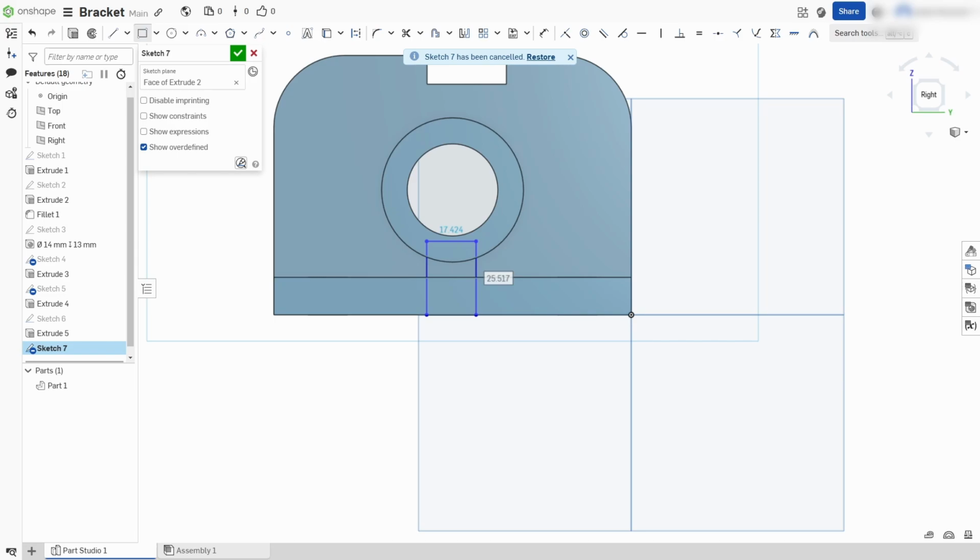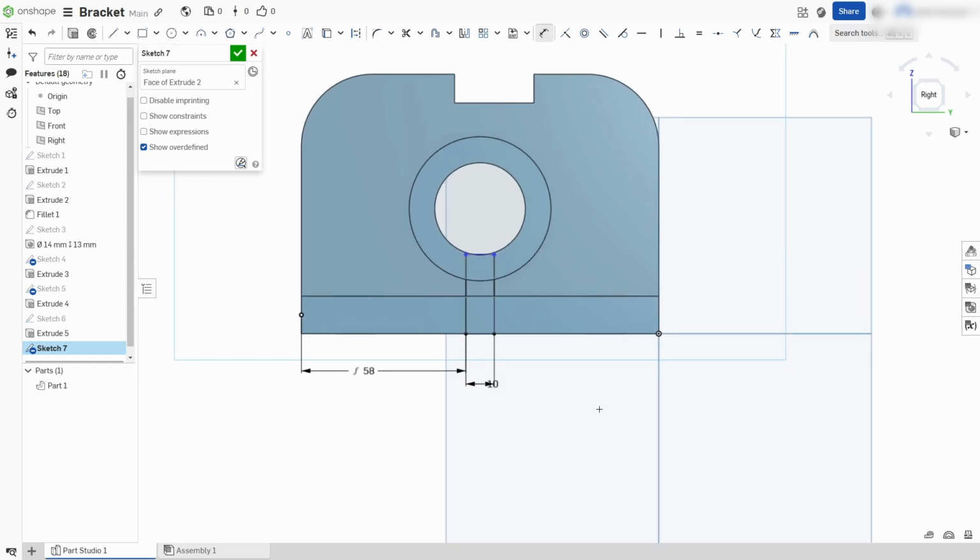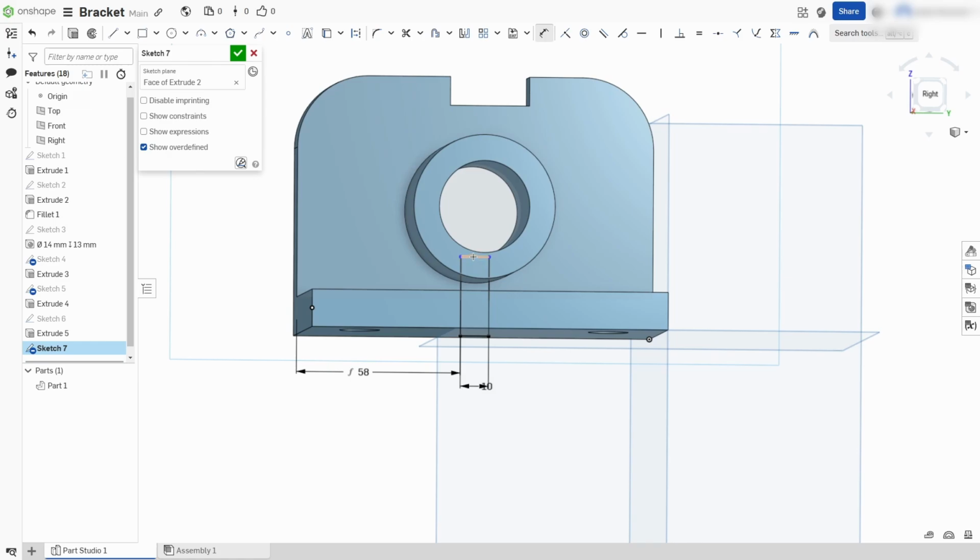Okay, and then this is 10 wide. So I'm gonna start this side here, 126 divided by 2 and minus 5. Alright, 58, there we go. And this should be 10. Okay, so that should be that. And then we can give this dimension here, here, here. All we gotta do is make sure it's less than going out. So let's do 25. Yeah, that should be good.